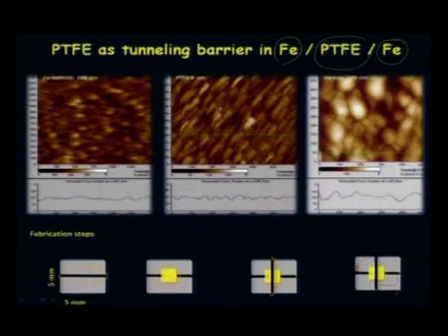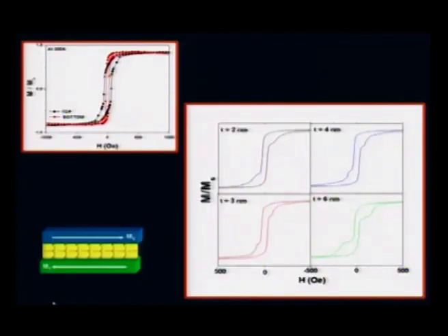The AFM of each of these layers is shown on top. You can see the microstructure is varying. The microstructure of the top electrode is quite different from the bottom electrode, because you are heating this sample during deposition at 250 degrees C. Therefore, you get a fine-grained structure compared to the amorphous room temperature grown film. Once you make this film, you can measure the resistance by applying voltage across these two ends, or you can apply current across this and measure the voltage across these two leads.